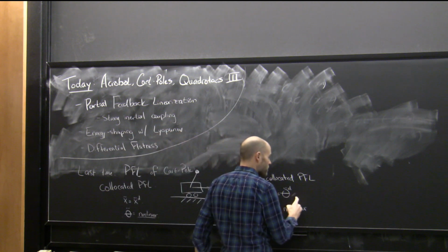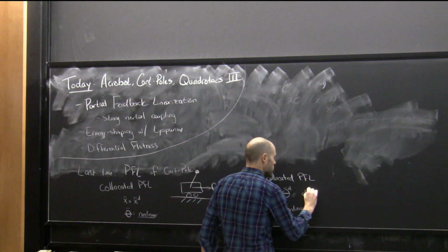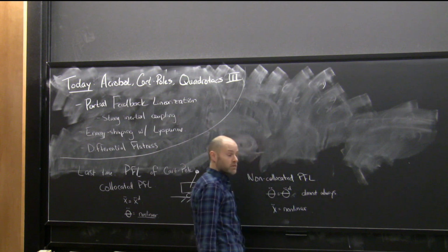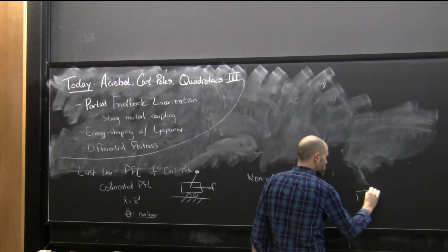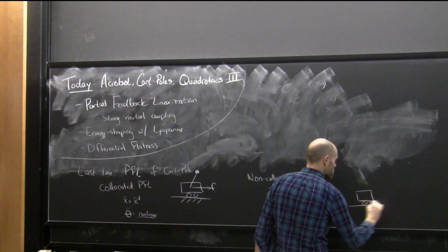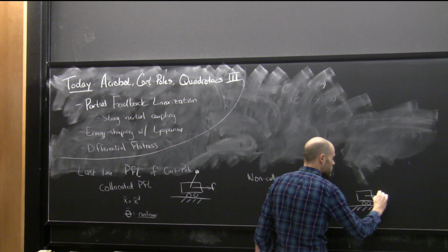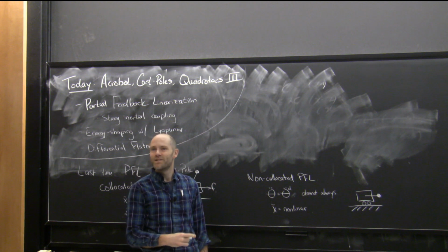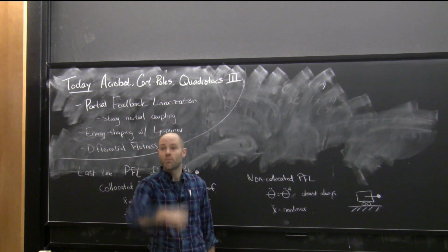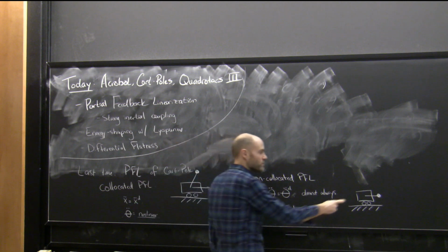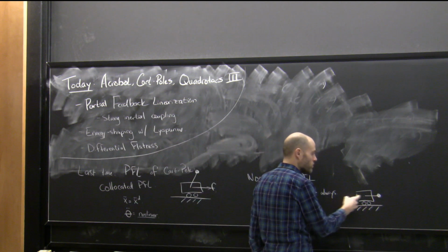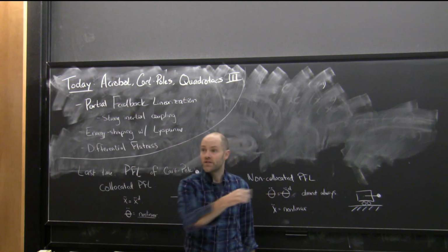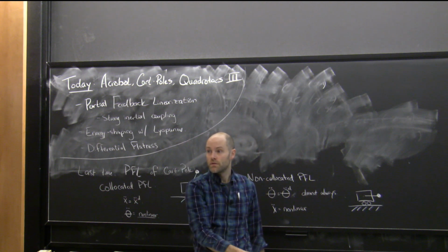But it doesn't actually work all the time. In particular, we saw in the simple equations we wrote that when the cosine in the denominator went to 0, my controller blew up, and that was equivalent to whenever the pole was exactly horizontal, because nothing I can do with the force instantaneously could affect the dynamics of the pole.